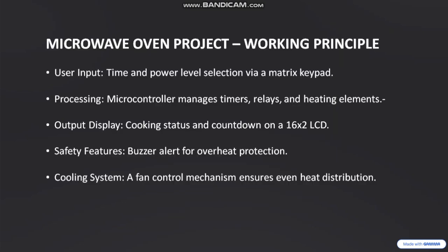The working principle of this project is: first, the user selects the mode and enters the time using the keypad. The microcontroller processes this input and the time starts counting down. The relay controls the heating process and the LCD displays the remaining time. When the time reaches 0, the buzzer alerts the user.